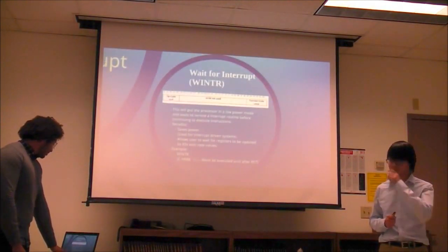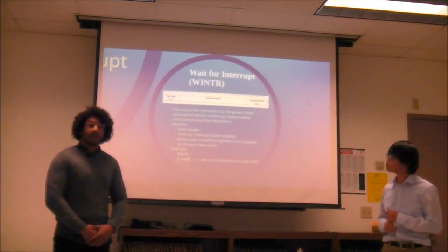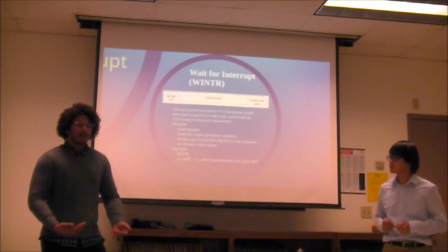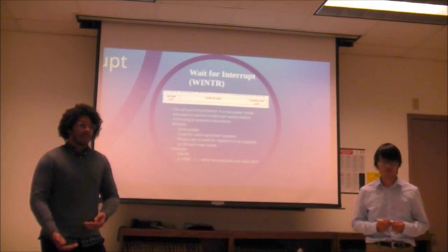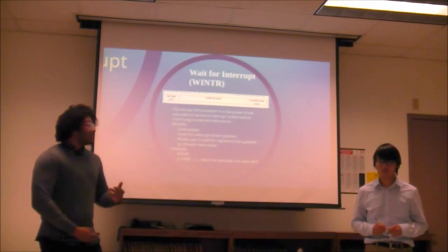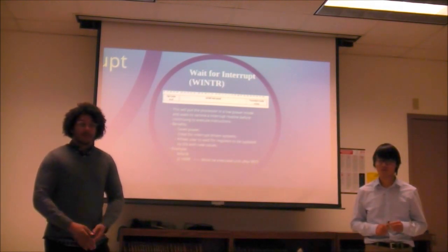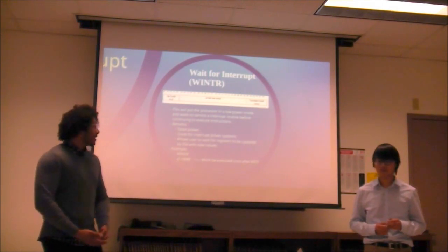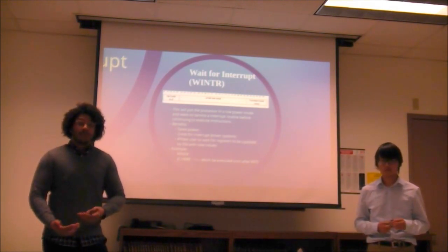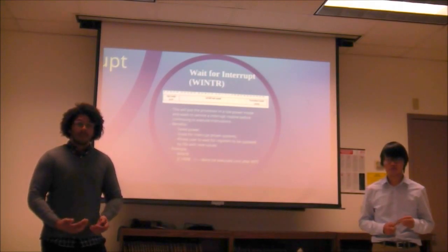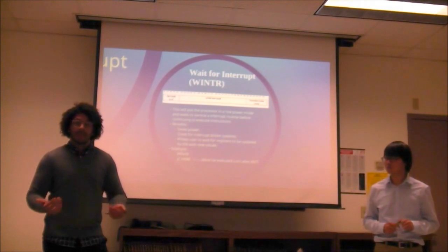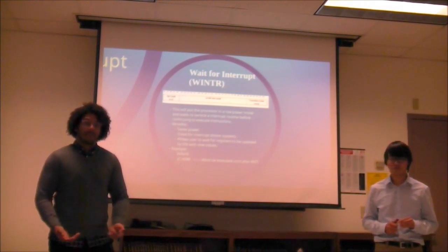Thank you. Then we also implemented a wait for interrupt. This allows you to put the processor in a lower power state because there's no switching of the electrical signals. It saves you power, so when you don't need your processor constantly running, it will go into a low power state. It also allows the user to better control the flow of their code, as well as wait for IOs to update certain registers if need be.